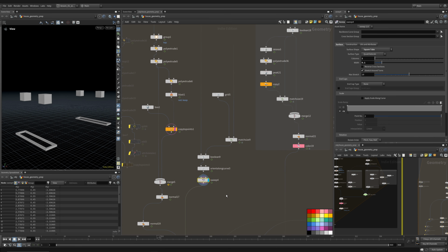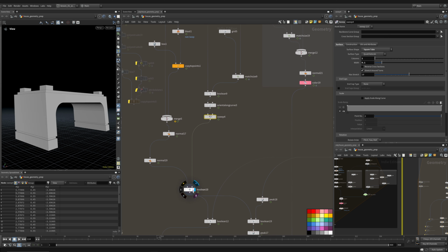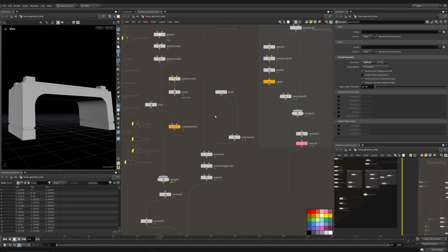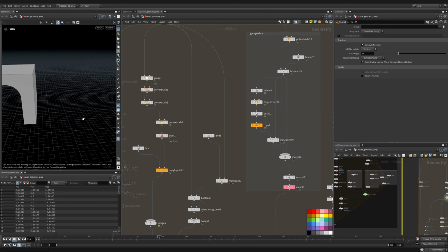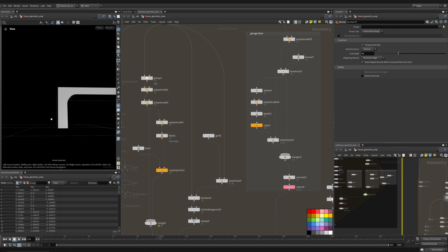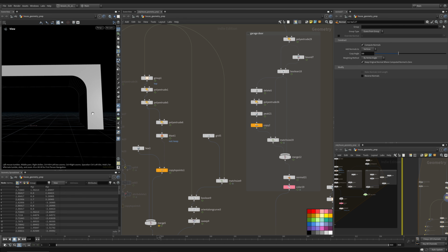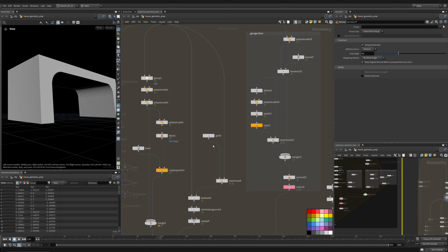So now what this does is this creates this inner sweep area, which we'll use to Boolean and cut out this bottom ridge. And the way that's done is, again, we get this input geometry. We're going to create a line, space G to frame. We're going to create a line along the base of this geometry. And then we're going to sweep that line to give it thickness. And then we're going to Boolean this object here minus that new line with thickness.